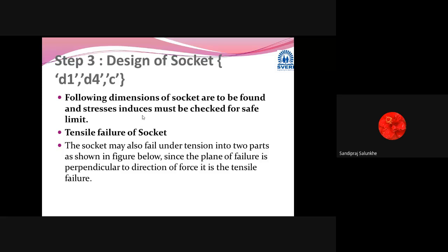Let me clear you once again that when we consider the stress to design these components, it means that we have already decided what factor of safety we are going to use for this component. Directly SYT or SUT, that is yield strength or ultimate tensile strength, we are not going to consider in the design formulas.